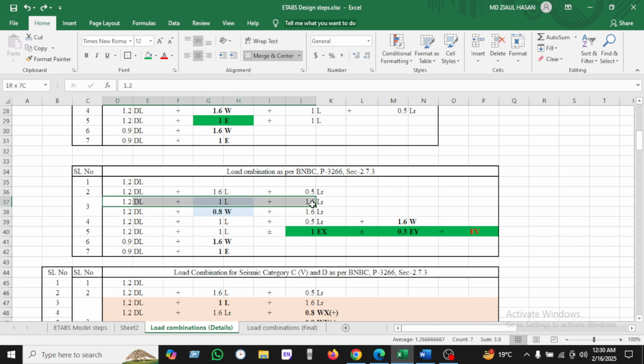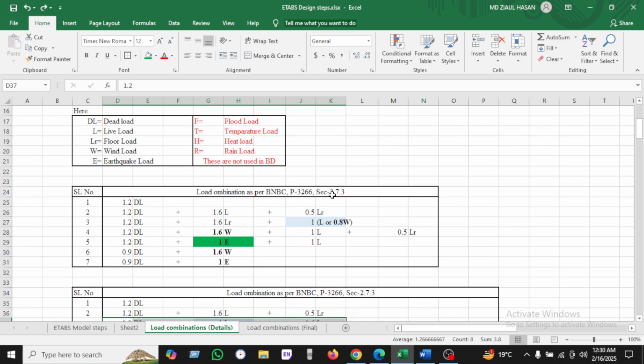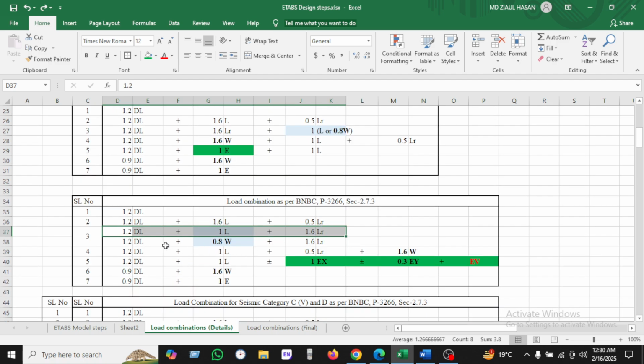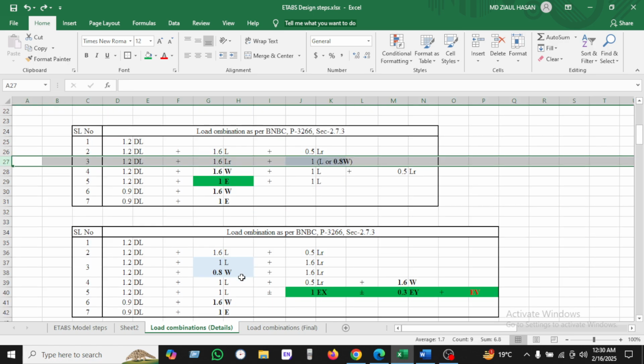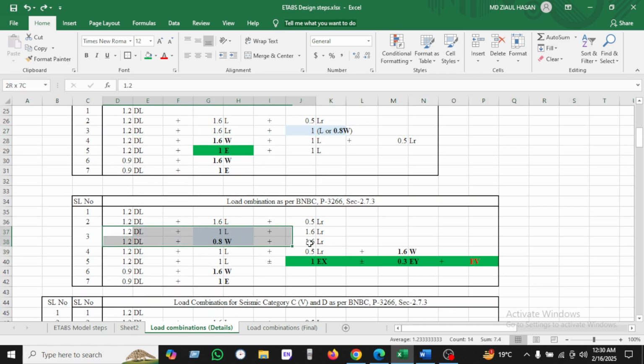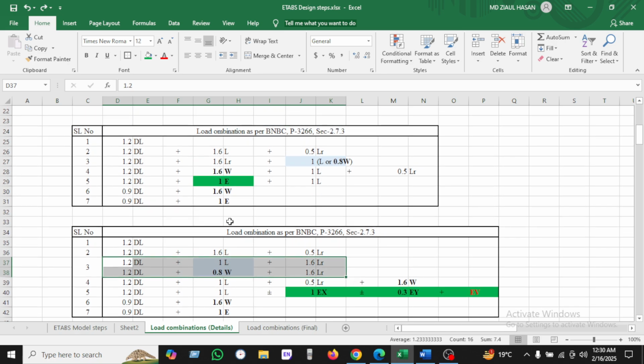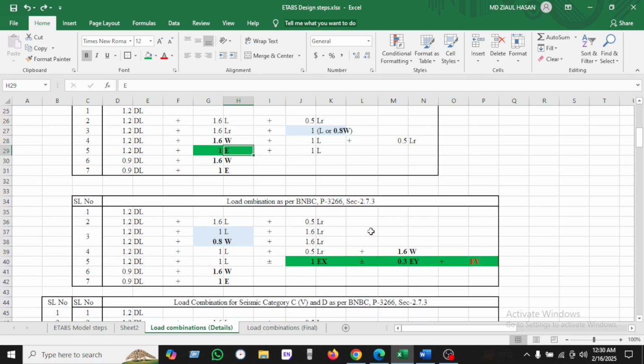One combination is for live load, 1.2 dead plus 1.6 roof and 1 live load, and another combination is 1.2 dead, 1.8 wind and 1.6 roof load. That's why we are dividing into two. We are dividing this combination into these two combinations. Okay. And we can see here the earthquake. As we know, the earthquake is divided into 3.